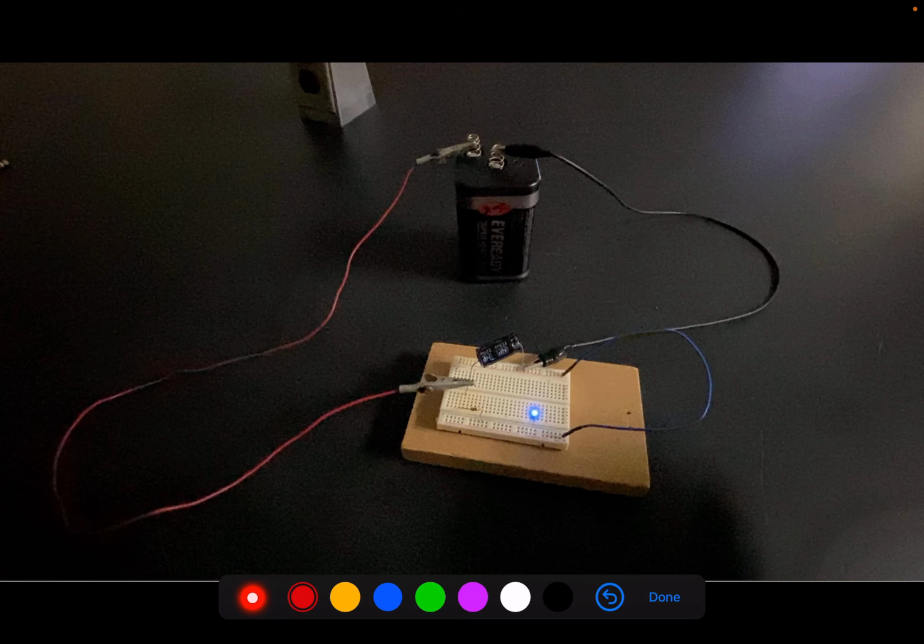Now, the two important parts are the initial conditions and the final conditions of this circuit. So initially, we have our capacitor fully charged at 8 volts, fully charged at 400 microcoulombs, and when we throw the switch, we get a certain current. I'd like you to realize you can predict that current by doing the voltage divided by the resistance.